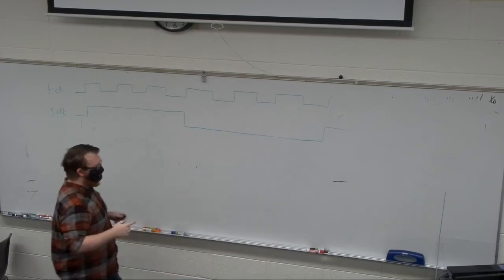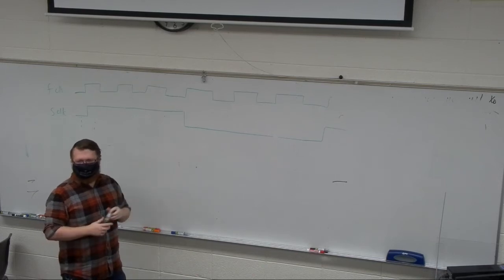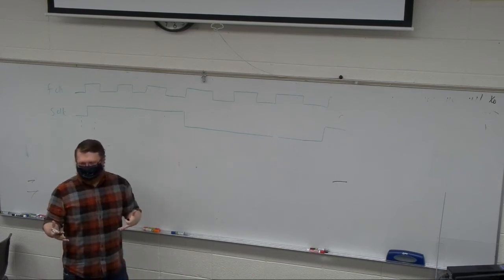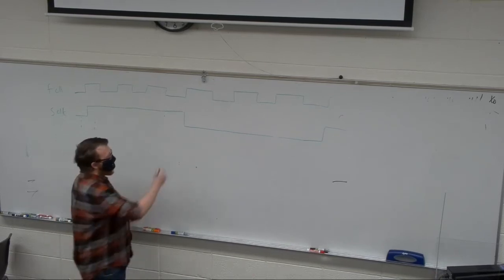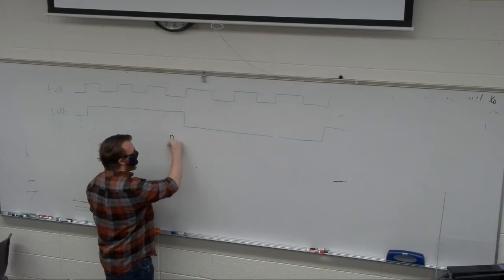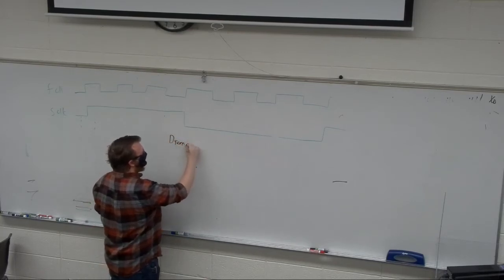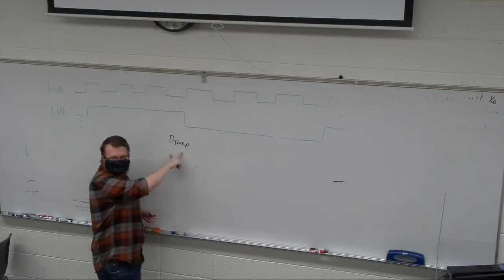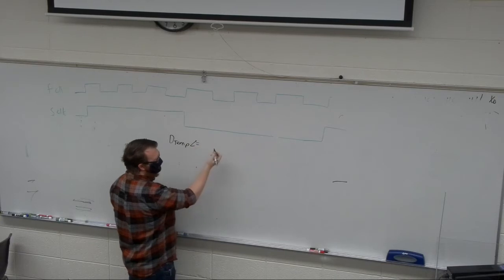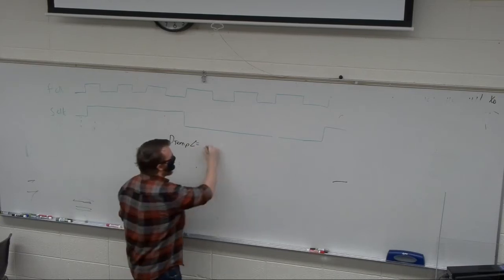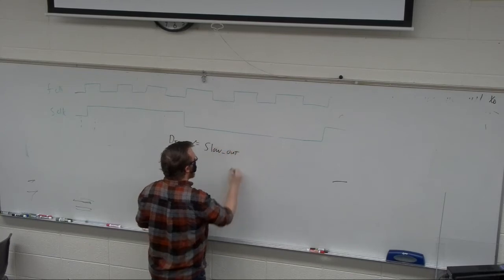Oh, something I should point out, for the 2 FIFO, the debouncing method, all you have to do is create a temporary signal if you actually wanted to implement this. So you'd say something like dtemp, the temporary data that's held in that metastability region, is equal to the output of the slow clock, so we'll call that slow out.